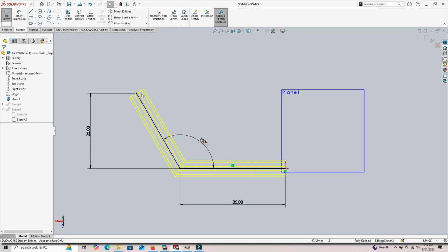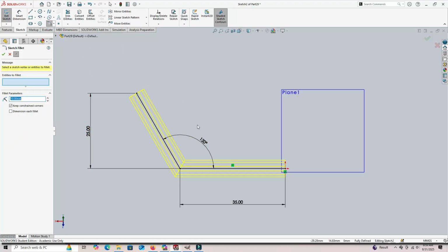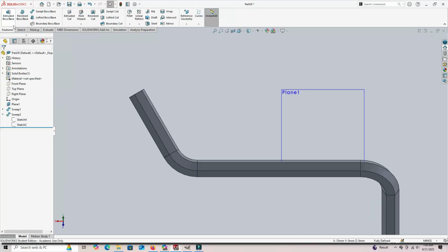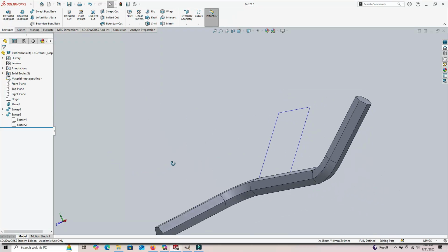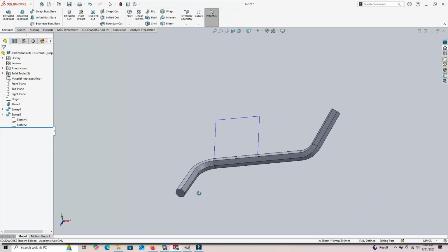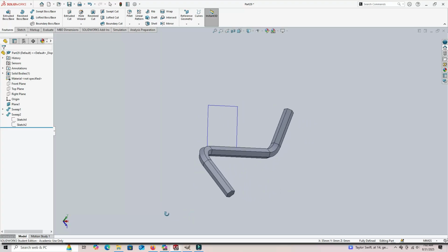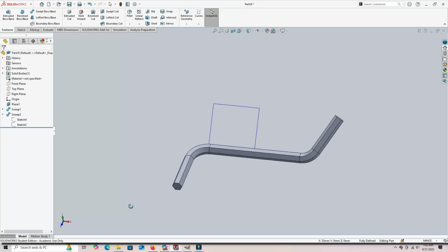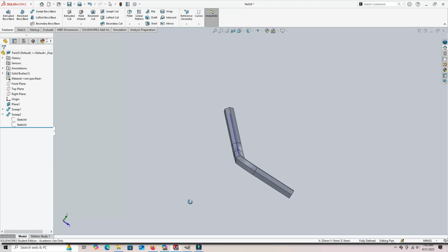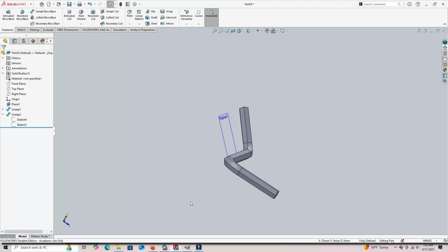and it shows you a profile, or a preview of the profile right there. I'm going to click fillet right there. It's already at 10 millimeters, and I'll go ahead and click that point. And now when I exit the sketch, there we go. Changed everything exactly as it should be. So now we have our finished part there, and you can see why we needed reference geometry for this particular thing. Otherwise there would be no way to get this bend at an angle to this one down here.